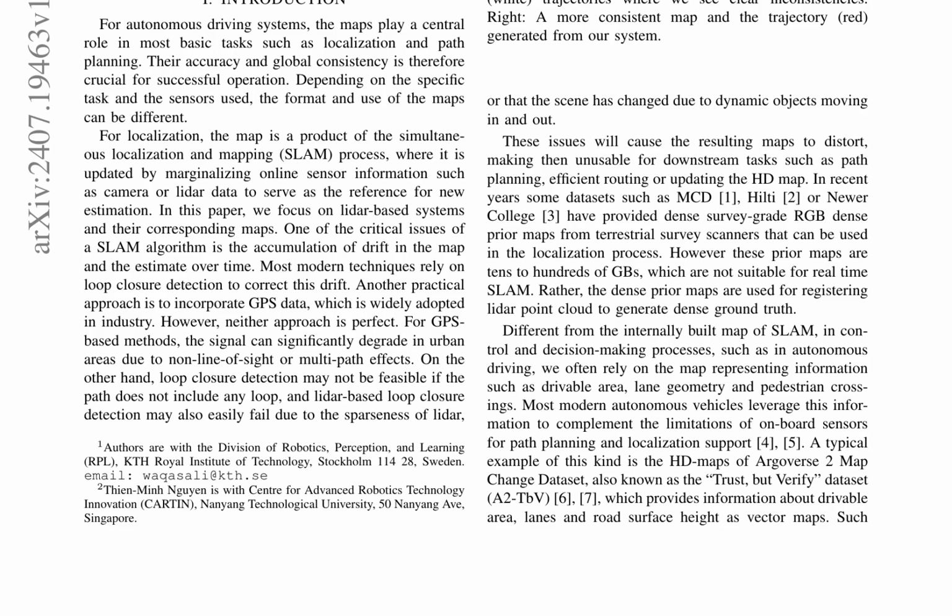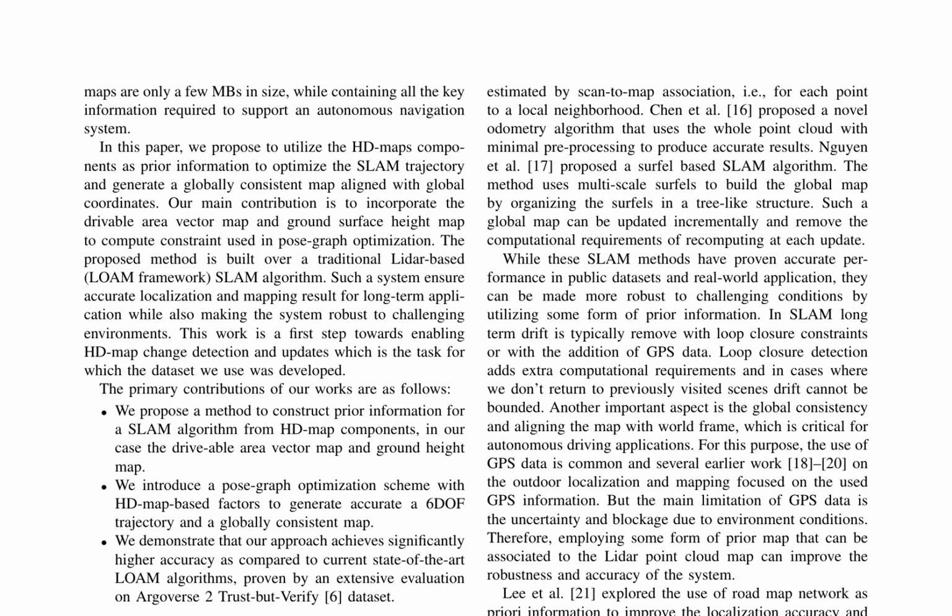The proposed method is built upon a traditional lidar-based SLAM algorithm and ensures accurate localization and mapping results for long-term applications while making the system robust to challenging environments. The primary contributions of this work include the construction of prior information for a SLAM algorithm from HD map components, the introduction of a pose-graph optimization scheme with HD map-based factors, and the demonstration of significantly higher accuracy compared to